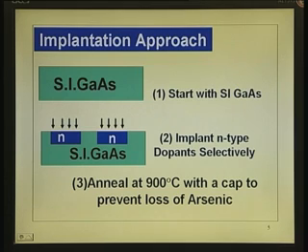Single machine, by controlling the path of the trajectory of the implanting ions, because the mass is different, that governs the voltage and the path. So, you can choose particular implanting species. At a time, of course, you implant only one. So, there is no question of choosing between them, but once you choose the material, you have to make certain adjustments so that the particular curvature path is followed. I am not going into details of implantation. That is more involved, maybe a couple of hours you will need for that. Let me skip that, but the general idea is you implant these ions, you get planar structure.